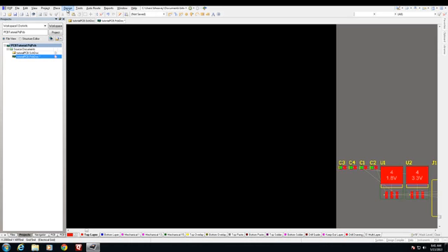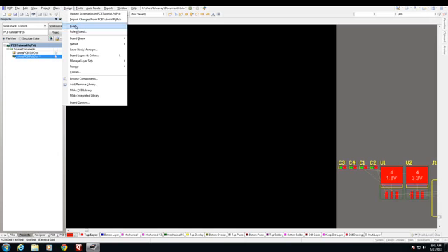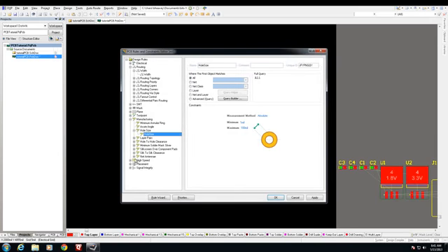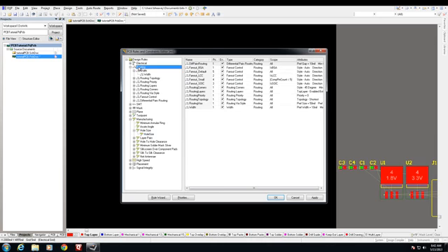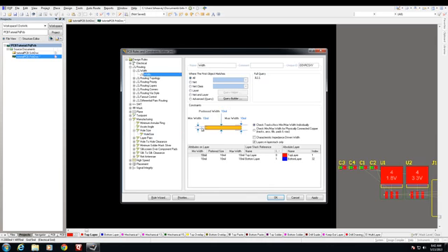To open up the design rules, we click Design Rules. This brings up the entire set of design rules for our PCB design. There's a few that we're going to go ahead and change for this particular design. The first is under the routing category, width. We can leave the minimum width at 10 mils, and the preferred size at 10 mils, that's fine. But we need to modify the maximum because we are making power traces and those need to be much wider than 10 mils. So let's go ahead and up this to 100 mils for maximum width for our top and bottom layers.